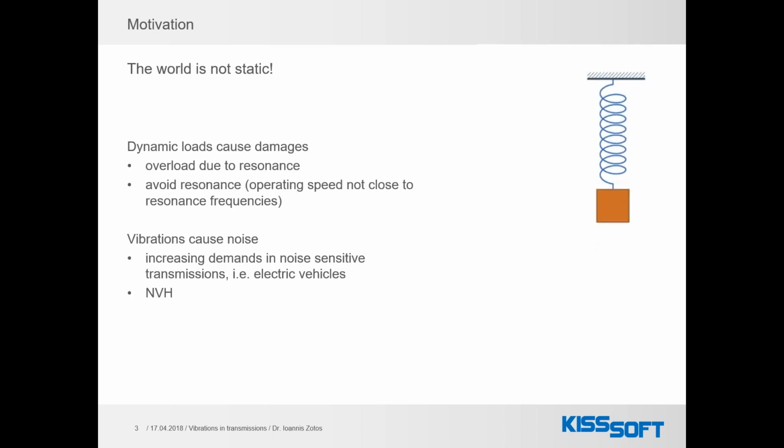So the motivation for calculating dynamics in the first place is, of course, that the world is not static. Dynamics is a very important part of, or should be a very important part of, any design work, because dynamic loads can really cause damage. There can be overloads due to resonance, and we should avoid any resonance situations where the operating speed is close to the resonance frequency of the structure.